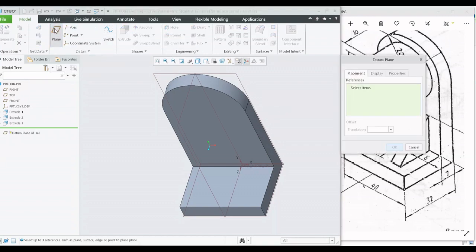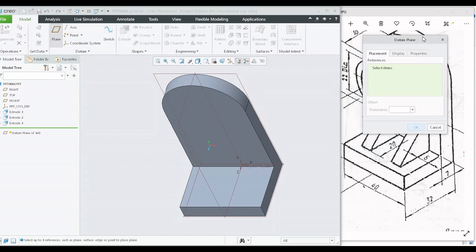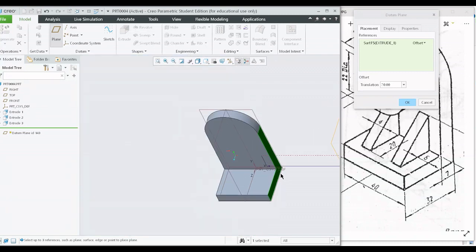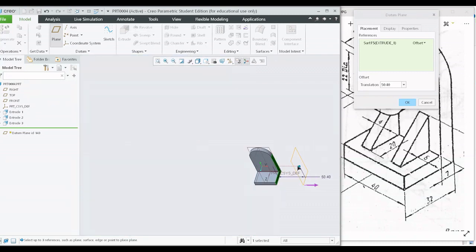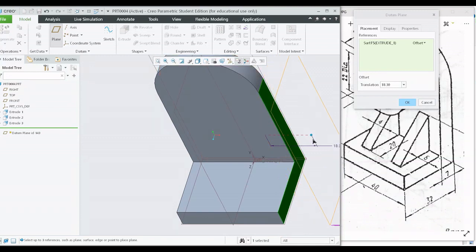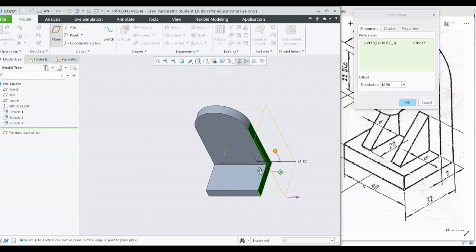So simply click on plane. Now we need a referencing. If you can see in the geometry, the profile rib is referenced with respect to the outer edge. So you can try to select this particular face. And let me just zoom out. I got my plane very far. So I have this plane referenced with respect to the face I've selected right now.